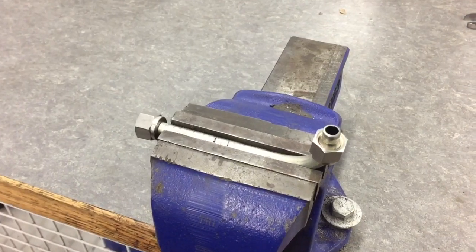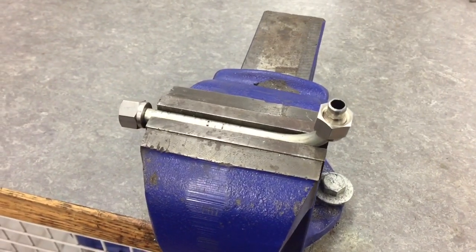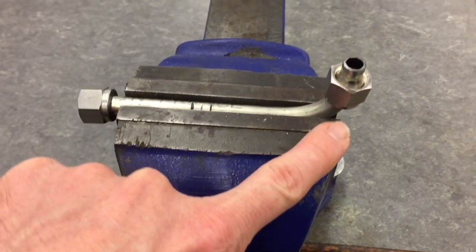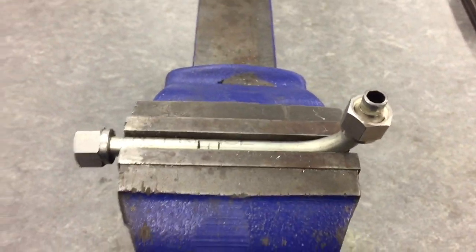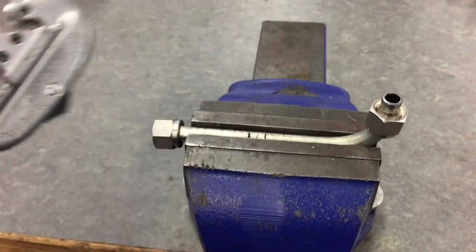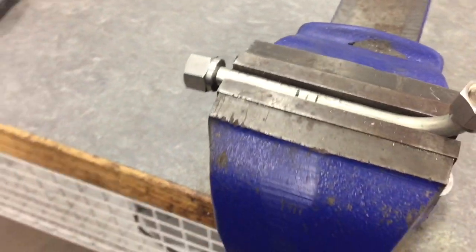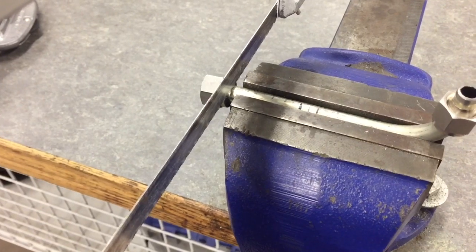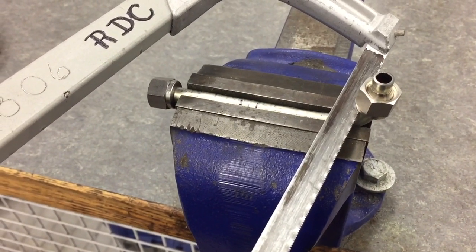So when we're all done with the tubing, we're going to want to cut off these nuts here to reuse them. You can see this bend here. We've got a 90 right here close to this nut, so using tubing cutters won't work very well there. So when we are cutting off these nuts, we'll just use a hacksaw and cut the tubing right close to the nut. We can do that for both of these here. Cut them off with a hacksaw.